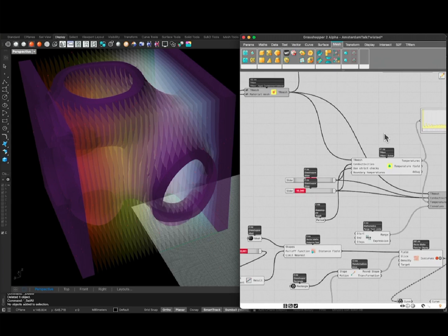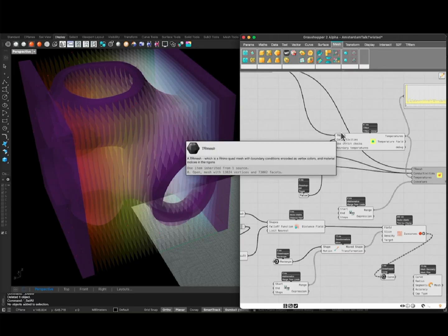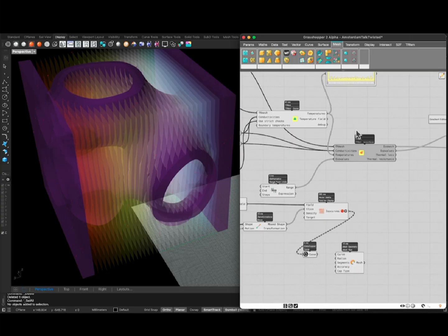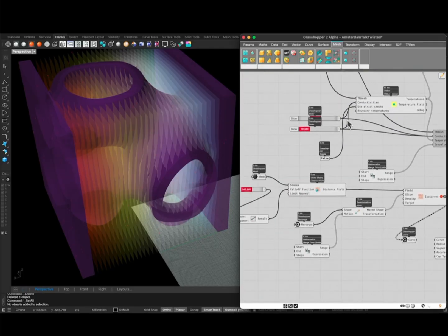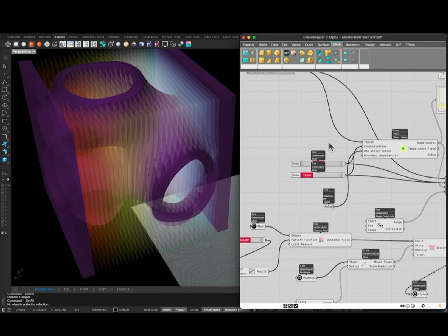We just plug it into a solver component which just takes such a mesh, interpreted as a tetrahedral mesh. It takes the material conductivities and it gives you the temperatures, which we can then plug into a usual marching cubes or isosurface component. And this is done in such a way that you don't need to wait overnight for a finite element analysis like this. This can be done in real time.